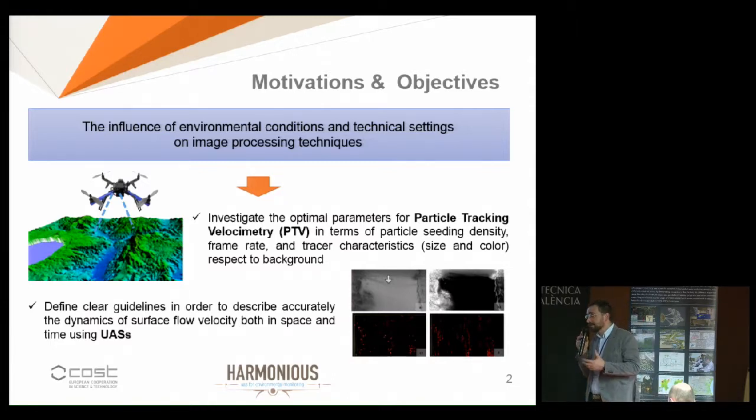The theory that these people have developed states that there is a clear and well-defined linear relationship between the mean velocity over the vertical, along the depth of the cross-section, and the flow velocity at the surface. The proportionality factor is about 0.7 to 0.75. So we know how to use these measurements.